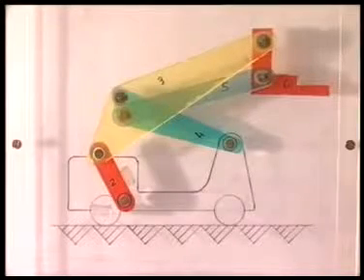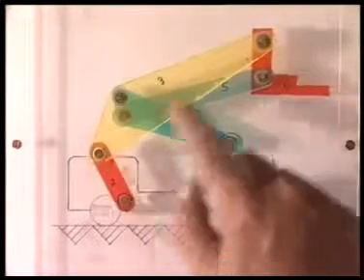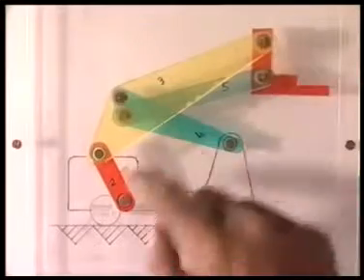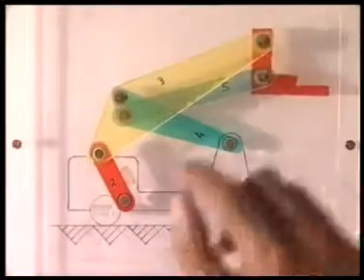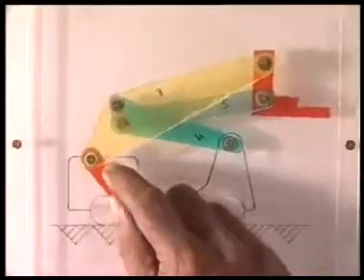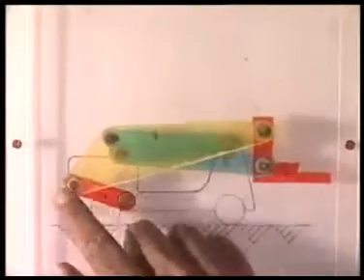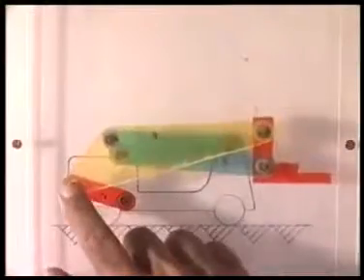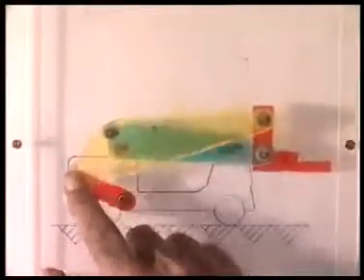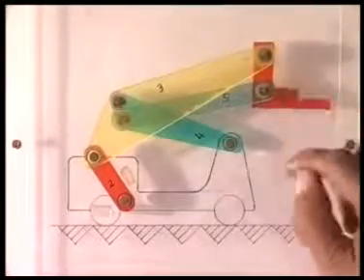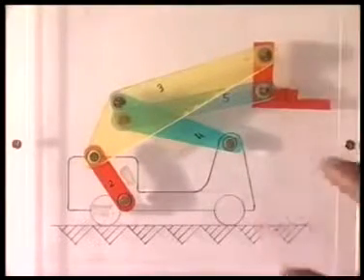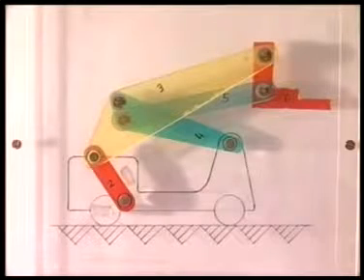So first we design O2AB as a slider crank such that the slider movement at B is coordinated with the input motion of the crank. 60-degree counterclockwise rotation of the crank has caused 1.5 meter vertical travel of this point B using 3 Chebyshev accuracy points in this interval.